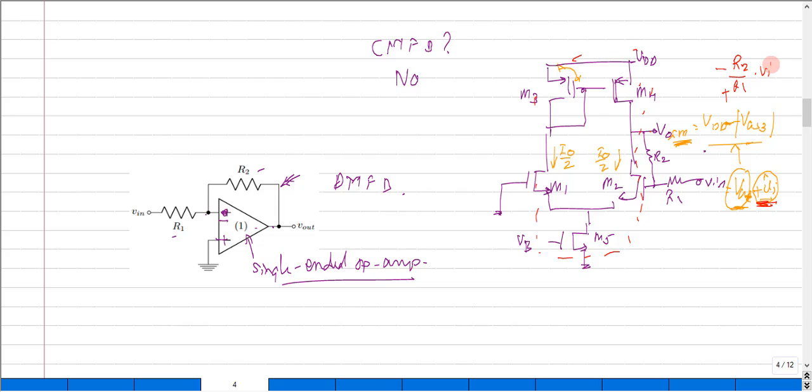So this AC component is basically under the assumption that the open loop gain of this particular circuit is very, very high. That is the reason why I could write this, and clearly this quantity signifies that the feedback loop we have created around R1 and R2 is related to the differential feedback component, and it is nowhere related to our common mode feedback network.